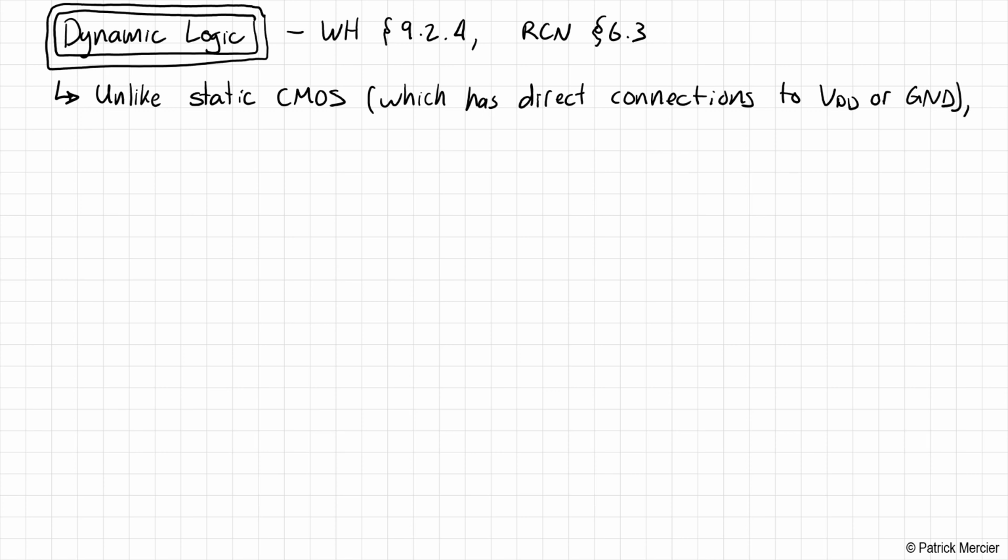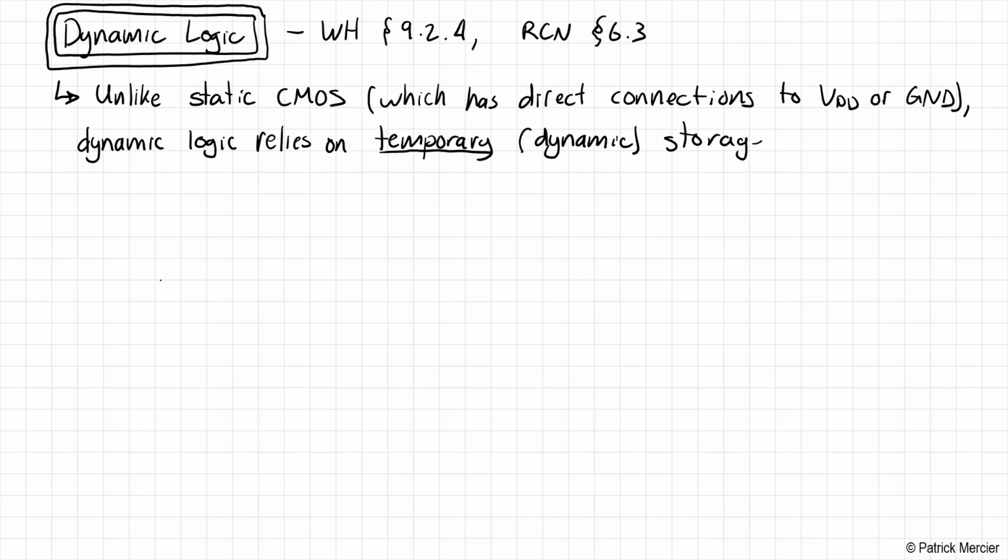So unlike normal static CMOS, dynamic logic, as the name may imply, relies on temporary or dynamic, hence the word, storage of logic values on capacitors.